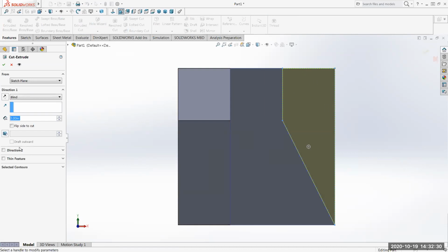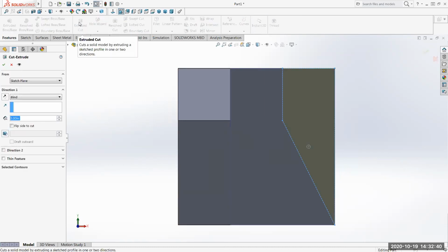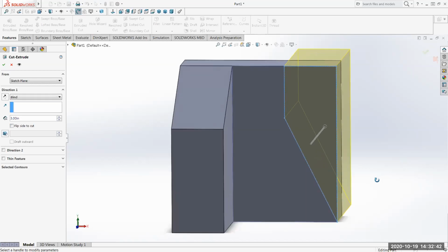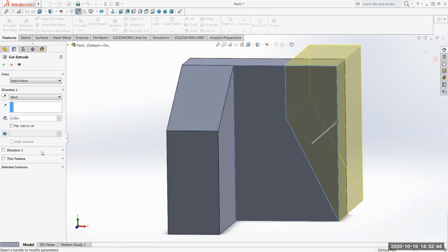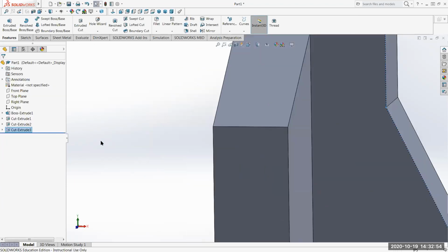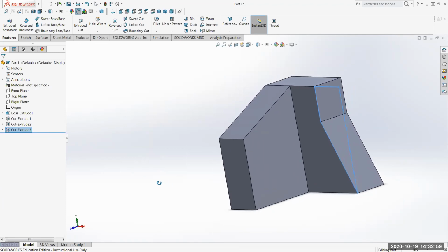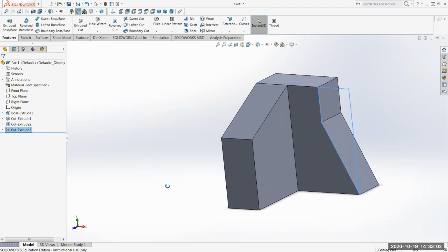So what I did was I just highlighted. Let me show you what I did. I highlighted the sketch here. That represents this sketch. And I took that and I said, okay, that's what I want to cut. All right, so let me spin this sideways. That's what I want to cut out. And yes, I'm going to change from blind to through all. I want to make that entire cut and check mark. Oops. Okay, so here's my finished product. And that looks just like the assignment sheet.